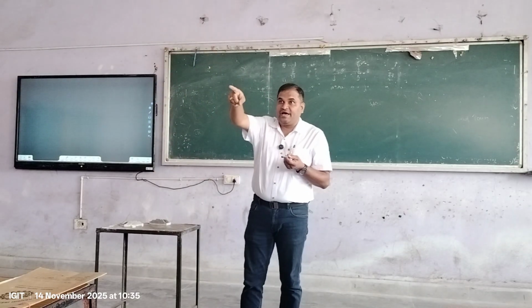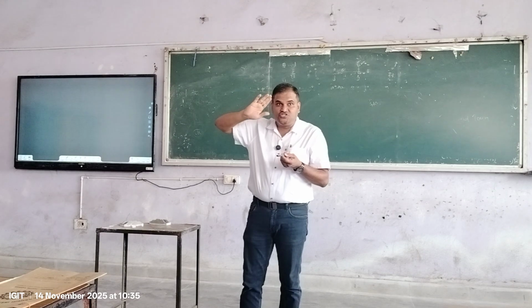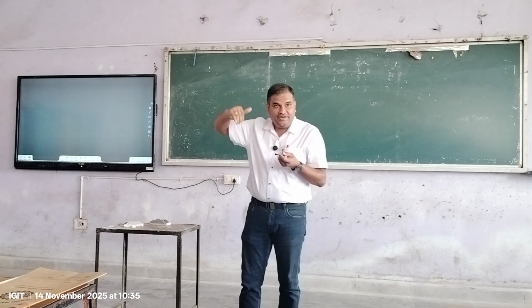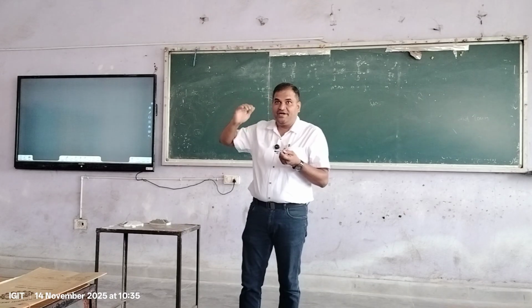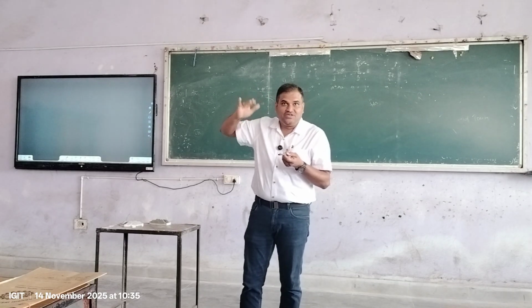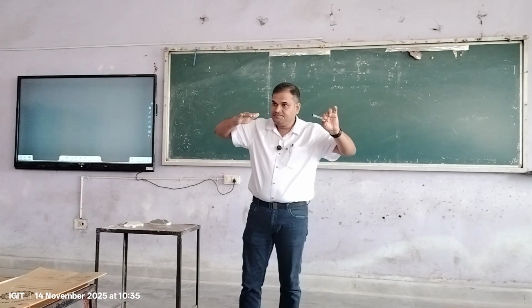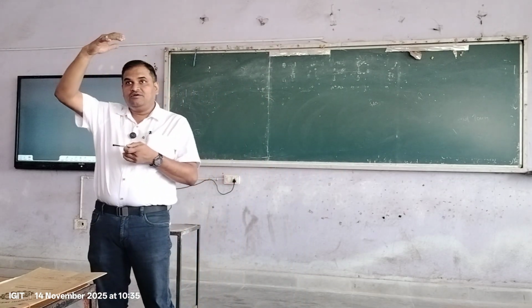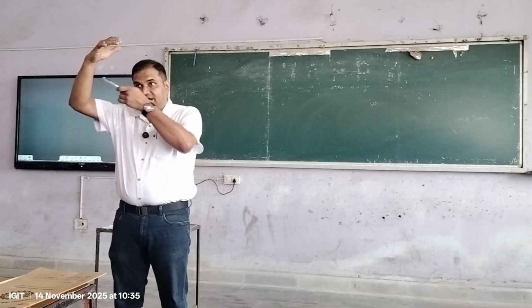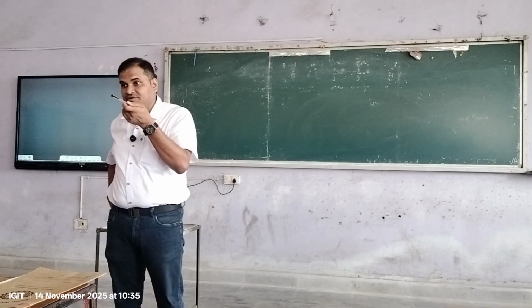ट्रांसफार्मर जो आपने पढ़ाई किया वो है स्टैटिक इंड्यूस ईएमएफ. वहां पर कोई चीज रोटेट नहीं कर रहा, सिर्फ करंट जा रहा है जो कि एसी है. The AC current creates an alternating flux like this, and because of that EMF is induced in the secondary conductor. But in case of induction motor, the flux is there, and since the conductor is in motion, initially तो कंडक्टर मोशन में होता ही नहीं है.